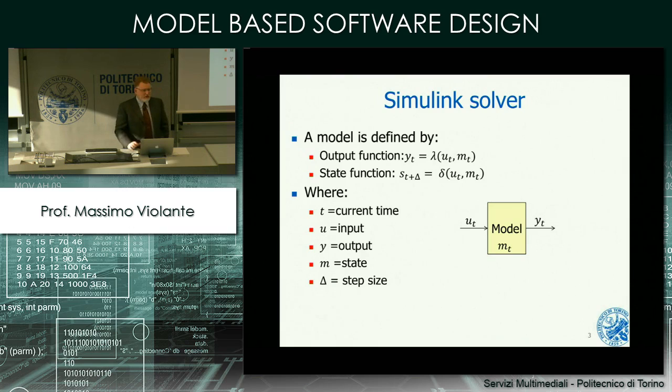When you look into the Simulink schematic, you have the capability of specifying for how long you want to do the simulation, the stop time. Typically it is 10 seconds, but you can write infinite if you want to have the simulation that lasts forever, or it could be whichever other number that is relevant for your application.